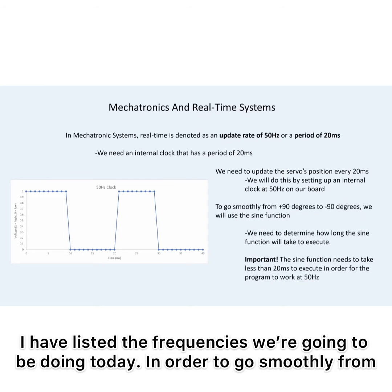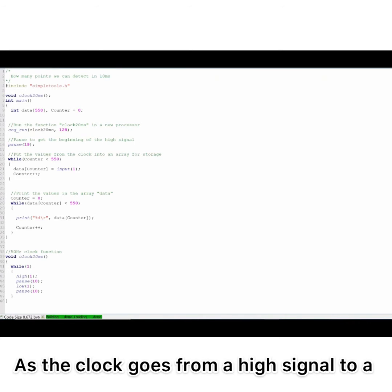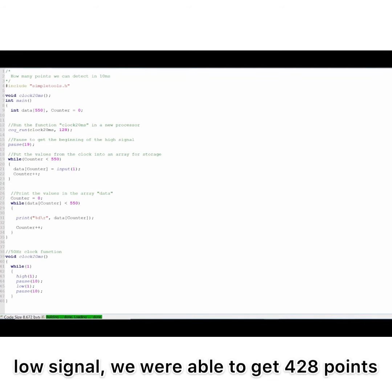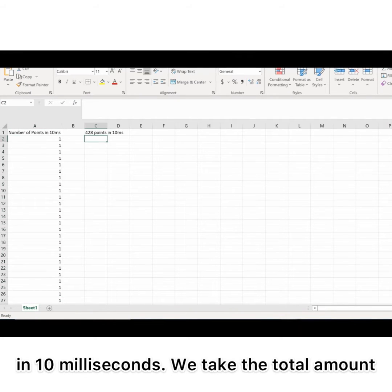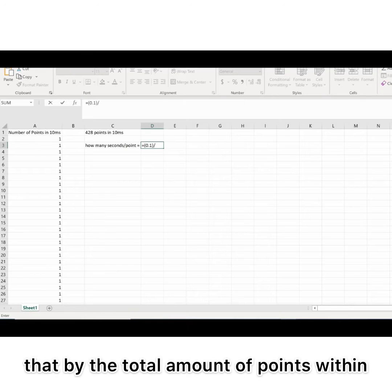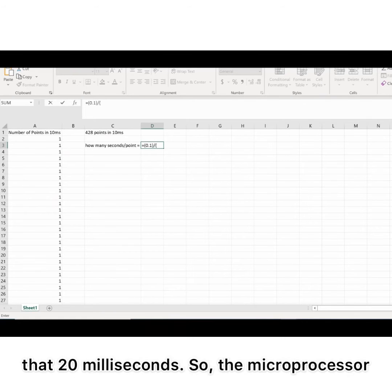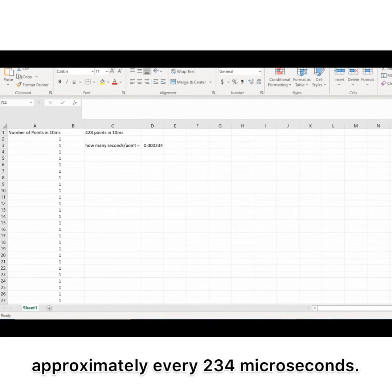In order to go smoothly from positive 90 degrees to negative 90 degrees, we will use the sine function. Because the clock goes from a high signal to a low signal, we were able to get 428 points in 10 milliseconds. We take the total amount of time, which is the 10 milliseconds, and we divide that by the total amount of points within that 20 milliseconds. So the microprocessor board can measure each point approximately every 234 microseconds.